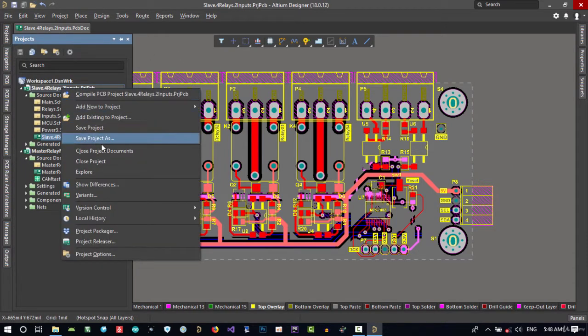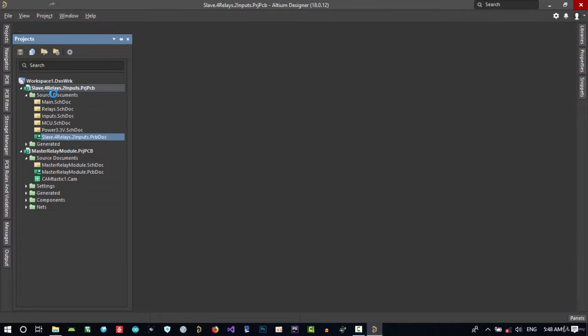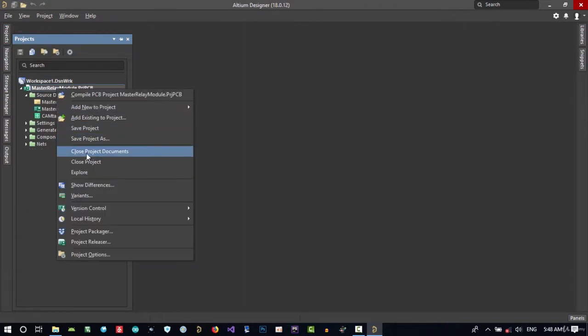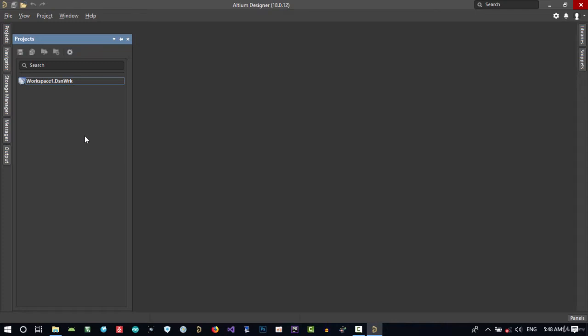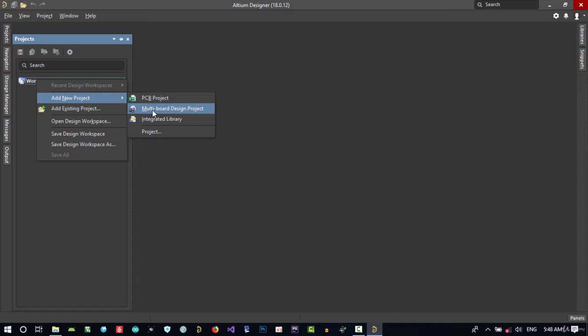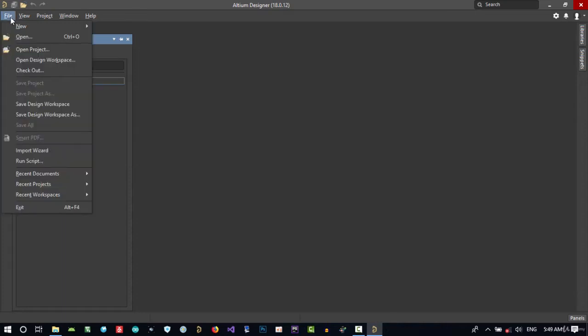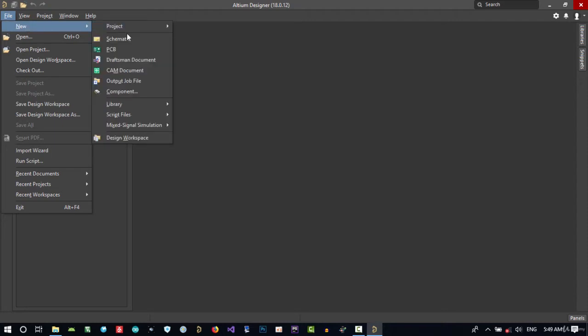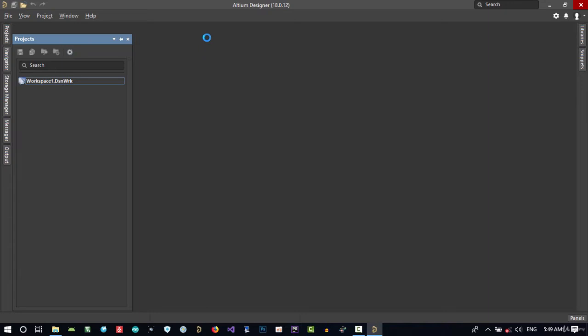Let's just close these projects. And I want to show you something, and that's called a multi-board project. If you right click here and add new project, you can select multi-board design project, or you go to file, new, project, and multi-board design project.